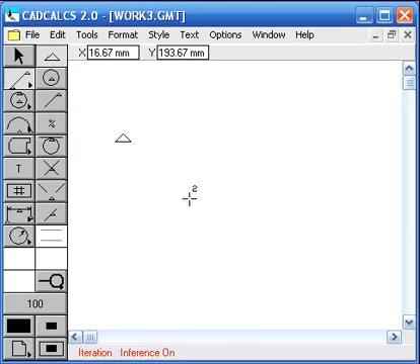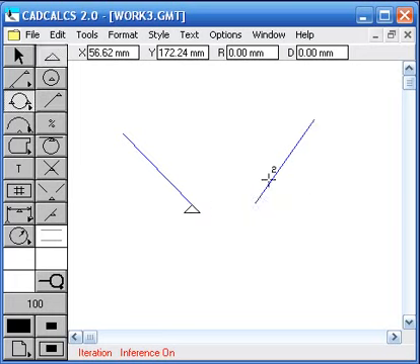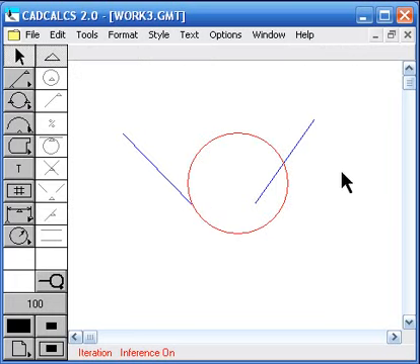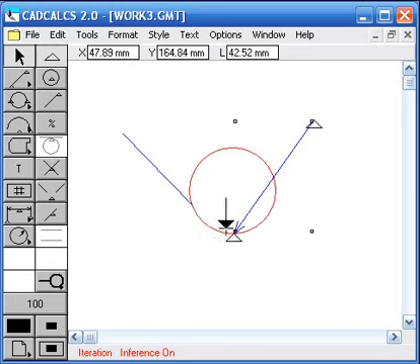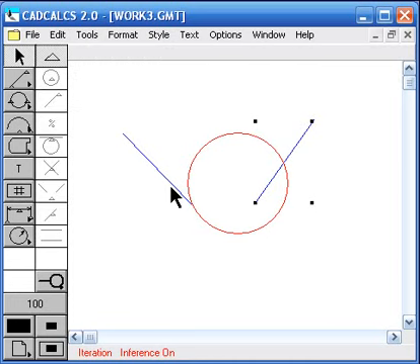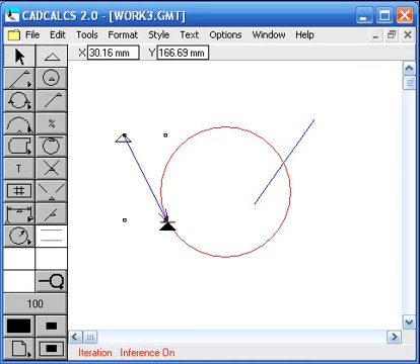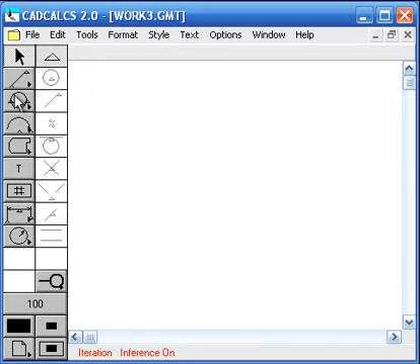And then you have a choice also. Let's say I have two lines here, and I want a circle which will be at the endpoint of this line, and let's say the midpoint of this line. So the radius is now defined by the location of these 2 points. And so if I change the length of the line, you'll notice that the circle is changing. Likewise, if I change the angle of this line, it's being changed.